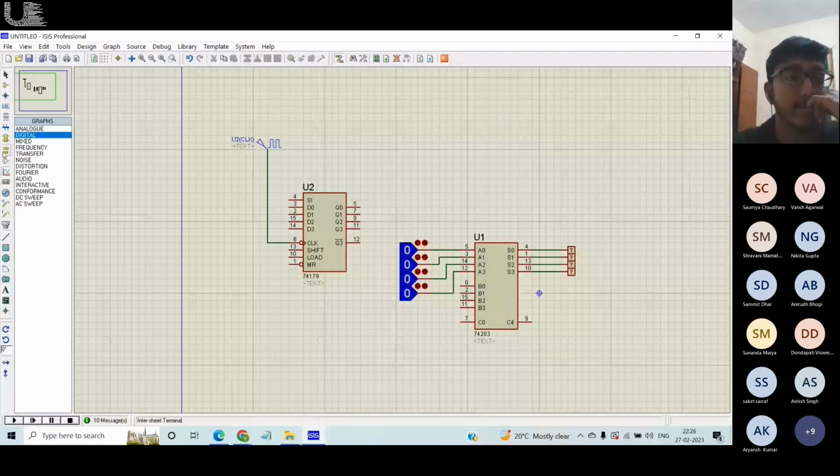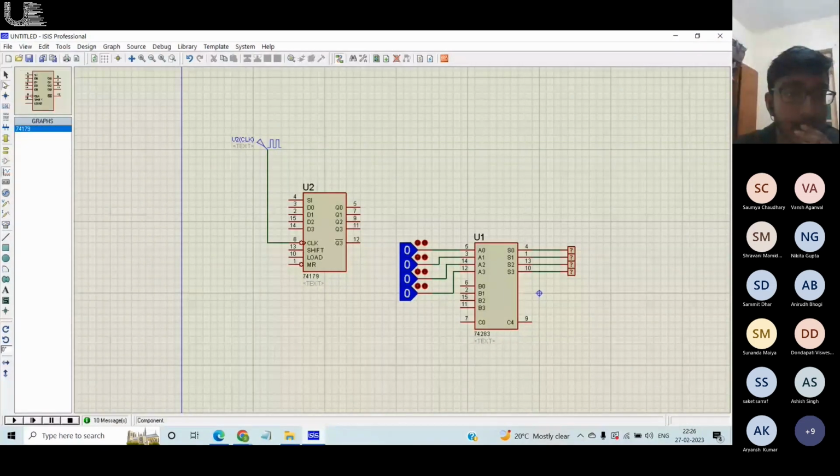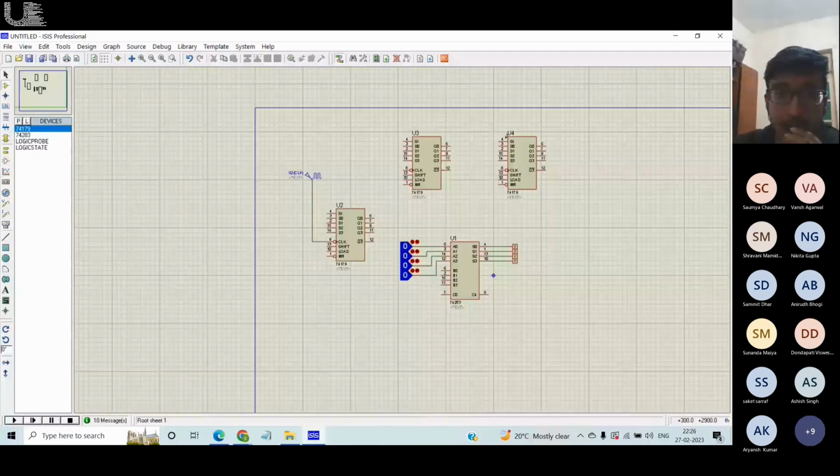Anything else is left? Yeah. The next part is, say, for a circuit, we'll be using only one clock, right? Your entire circuit will be having one clock or the max 2 clocks, but there can be many components which will be having the same clock. Like say if I'm putting maybe 5 registers, right? So connecting the same clock to different registers, there can be 5, there can be 10, there can be 20 registers you're having. So it becomes very messy, right? So what you do is